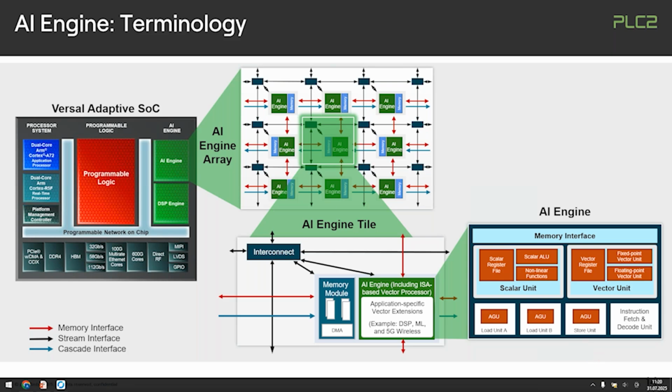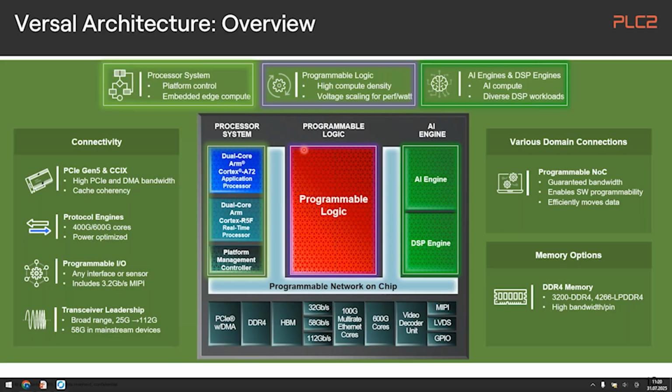So in the overall system design, you have these 3 elements. You have the CPUs, you have the programmable logic, and you have the AI engines. All of them are independently available on the device, but you have to organize the data movement correctly in order to get efficiency out of it. When you look at this particular picture, this means already, for somebody who knows embedded systems, that you will have to create instruction level components for the PS parts. It's just ELF code, basically. You will have to create the bitstream for the programmable logic. And these are actually going together.